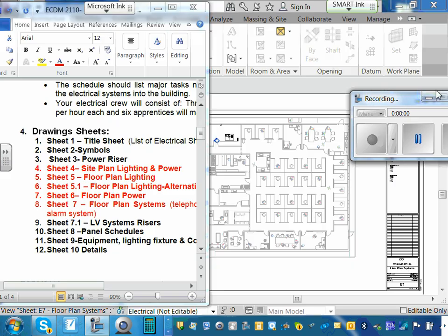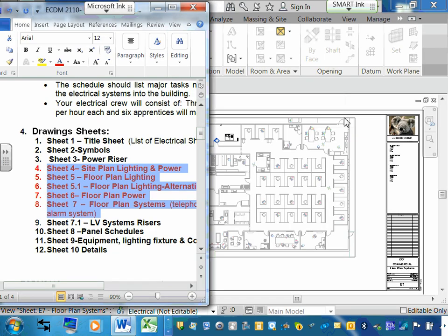Open yesterday, they need a view. These need a building view. The other ones will need what we call a drafting view. So let's go create a drafting view. What's the difference between a drafting view and a building view?